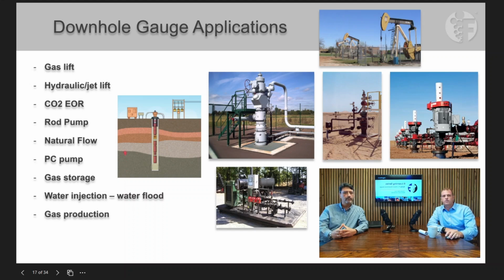Correct. Of course, another big one is any kind of pump application, jet pump or hydraulic pump, rod pump, and PC pumps. You can get that pump discharge or intake pressure, right? So you can monitor, maybe we need to adjust strokes per minute on a sucker rod pump, or maybe we need to adjust the hertz on the surface pump for a jet pump based off of that intake pressure, just like your PIP would be for ESP.